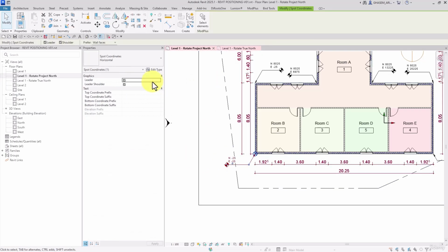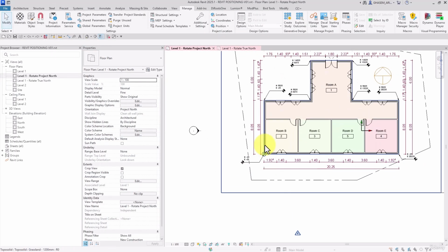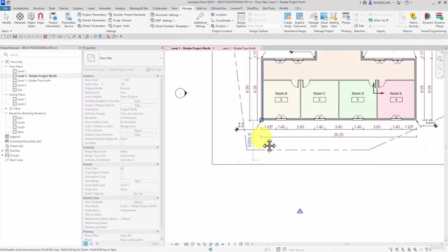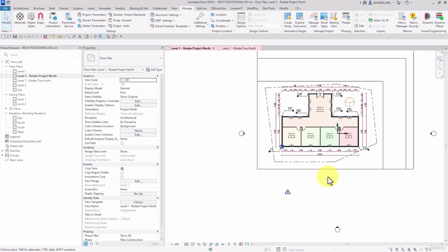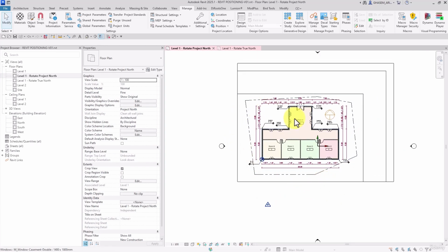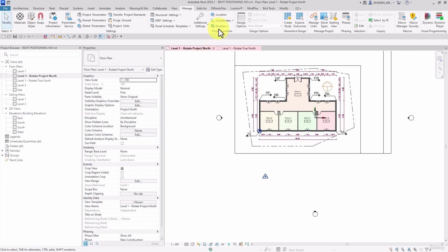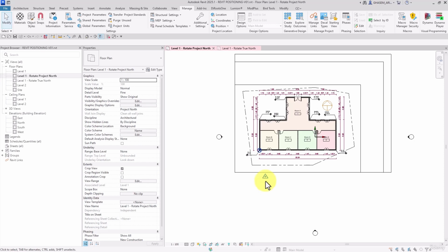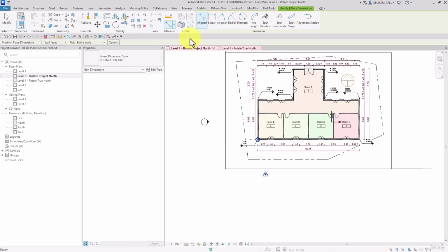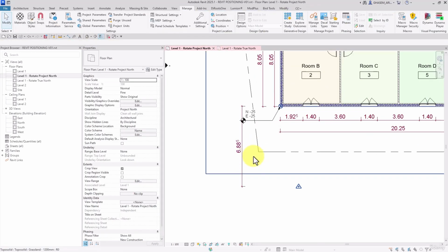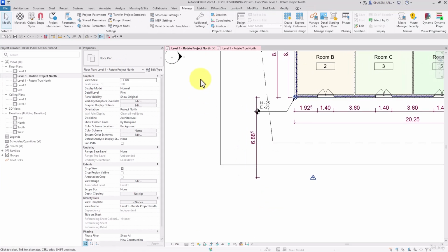Done. Select. And then I set it to the project base point. Then again, Relocate Project, or I can move it to another position. Then it will be relocated based on the specified direction, like this way. Again, this time 5 meters. Watch this, close to the survey point, and then Linear. There is 6.88 meters, the distance between the survey point and the project base point.